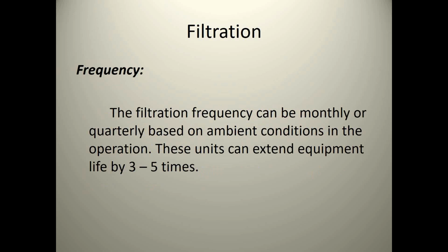Your filter frequency: how often should you use a filter cart? Well, you can use a filter cart every month, every quarter, but sometimes you have to pull some oil analysis samples to see how dirty the oil is, and then determine what ISO code you want to get it down to in your filtration system.